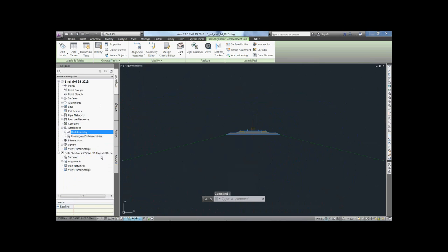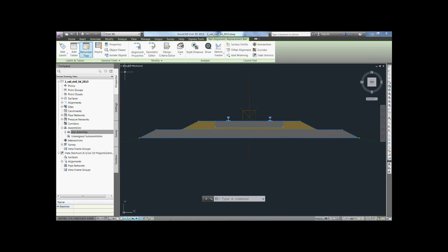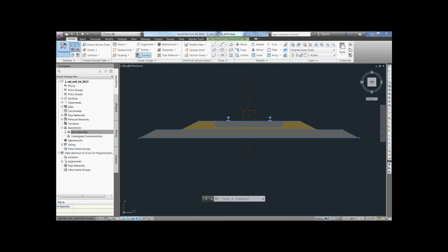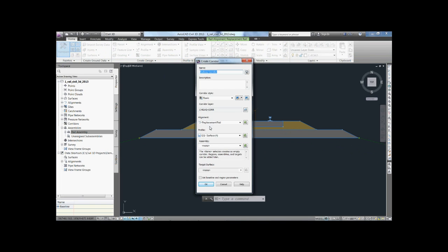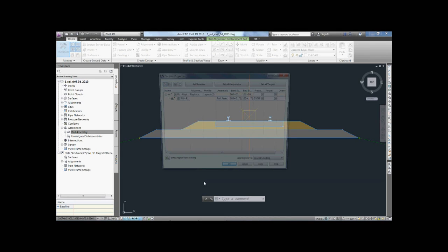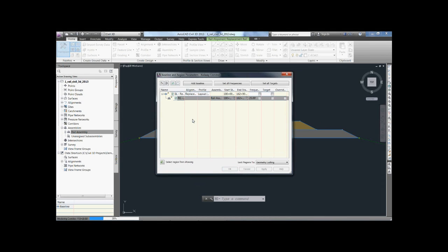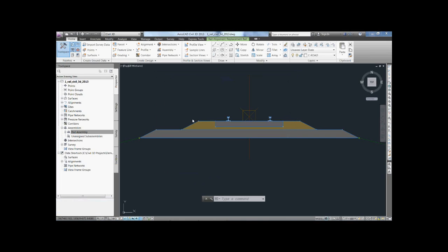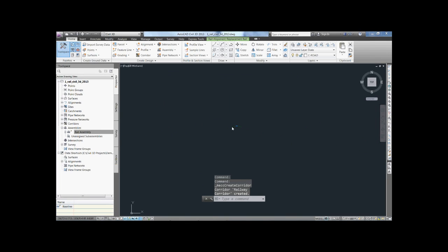Now that I've cleared out my violations, let's talk a little bit about building my rail corridor. Here we have our rail subassembly piece. This is the out-of-the-box piece. Once again, we can go into Subassembly Composer and customize this as we want. And now you're seeing our newly streamlined corridor creation. No more multi-step process. It's just a one-step process to build our corridor and target our surface.